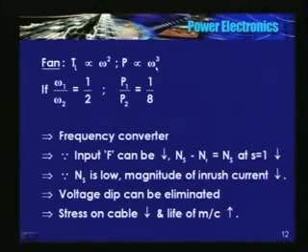Now if you want to reduce the discharge through the pump, or you want to reduce the air delivered by the fans. Now I am not talking about the 60 watt fans, I am talking about high kilowatt fans that are used in the industry. If you want to reduce the air discharge, what will you do? Either you use dampers, in other words dampers provide a resistance to the flow of air, or use a throttling valve for the pump to reduce the discharge.